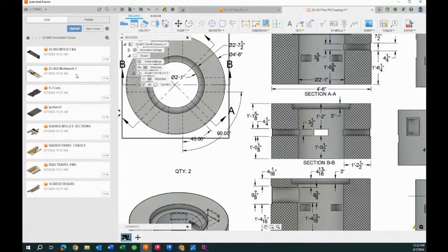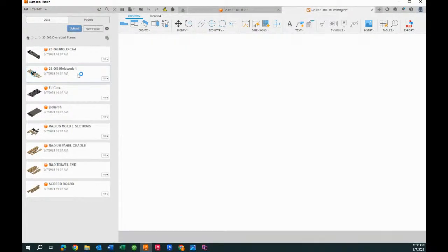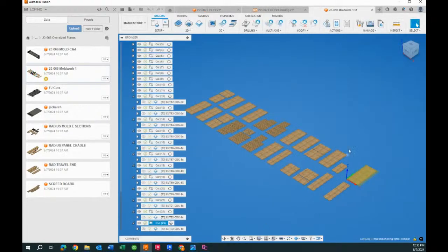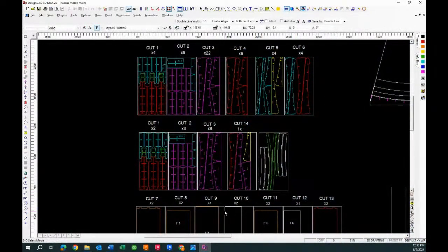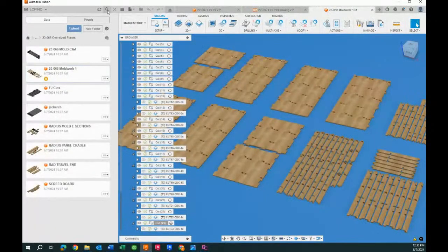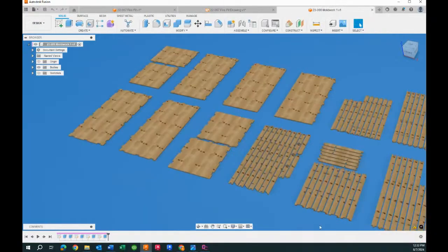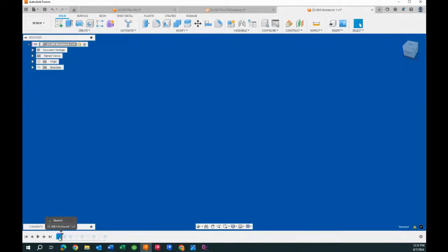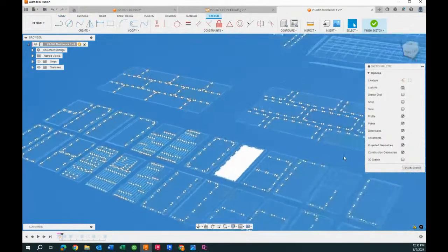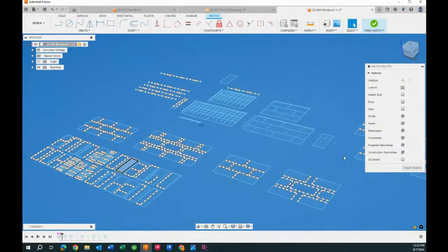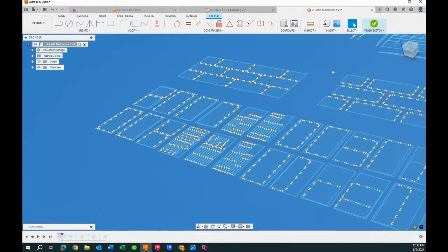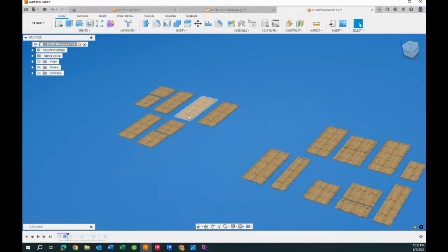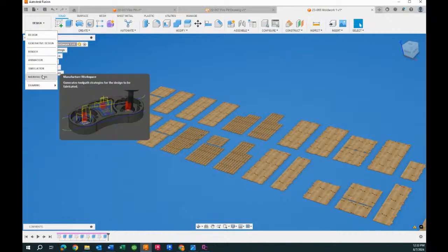So we would export, import, export out into, so you would push out that DXF, for example, one large DXF that has all this material on it, was pushed out to the Fusion 360. And in this particular case, you can import all of those individual sheets as one big part, so to speak, that is then extruded up into individual components. Then when I go into the machining element of it on manufacture,